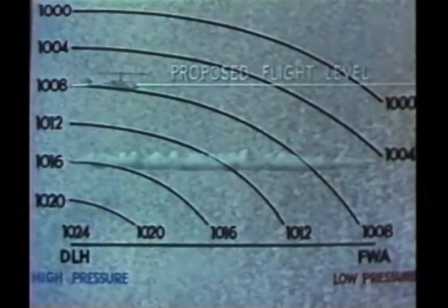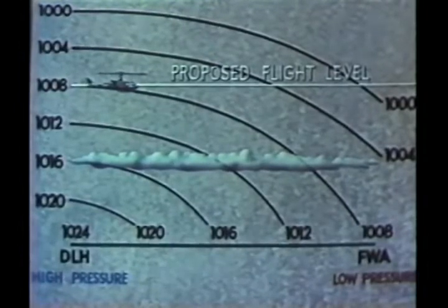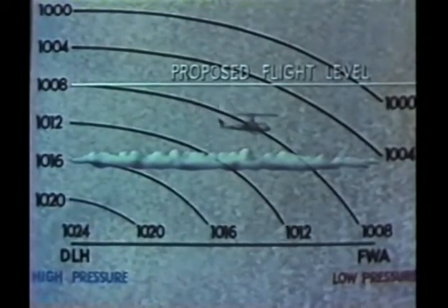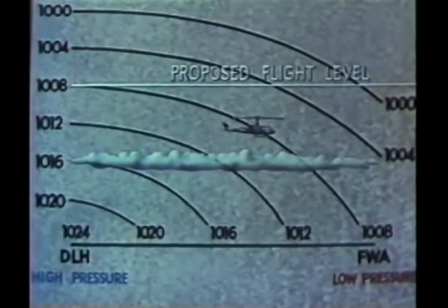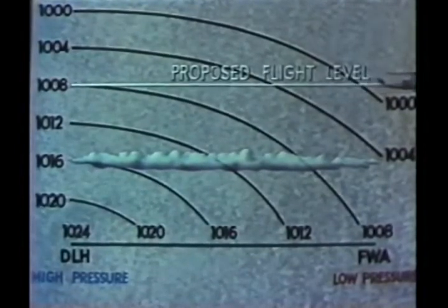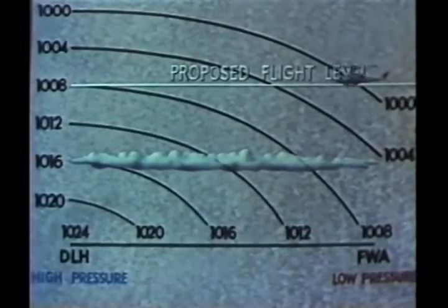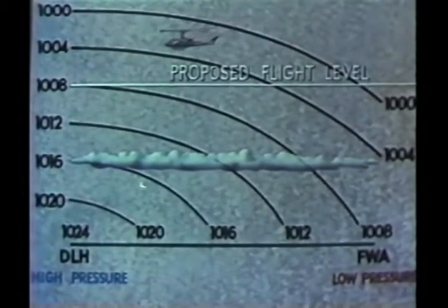On this proposed flight, if we flew a constant indicated altitude without correcting for the pressure changes en route, we would fly along an isobaric surface, and we would be flying lower than the altimeter indicated. In such cases, we should obtain a current altimeter setting and climb back to our proposed flight level. The reverse is of course true when flying into higher pressure areas. There are other altimeter errors which you will hear about in future instruction.